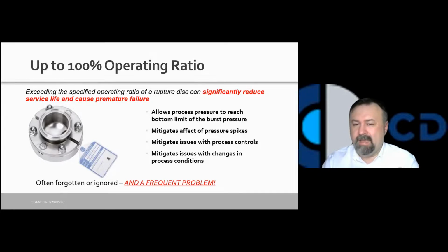So what would happen if you keep exceeding it? Because once you reach the minimum burst pressure, the disk is there to actually open and relieve the overpressure. So if you go into this gray area, you will simply fatigue the disk out faster.